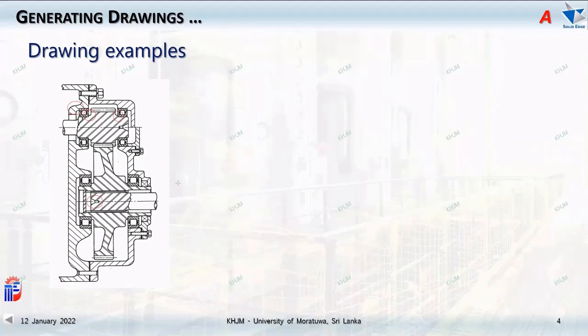the bearing outer ring is fixed, tightened using the end cap. You can see even in the bottom one, it is also the same thing. Now in this particular case, you can see both sides are fixed. You can see over here and also you can see here. Means nothing is free to move.